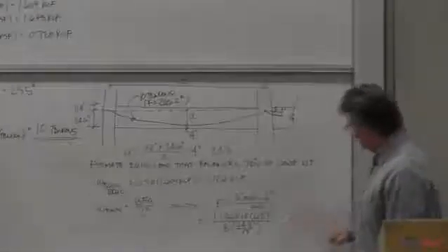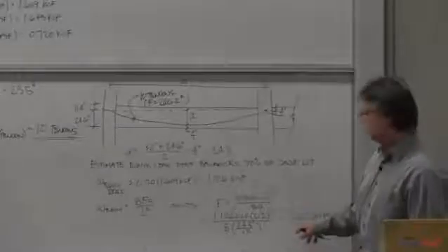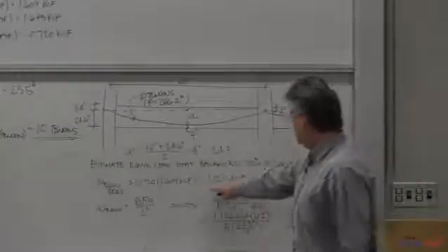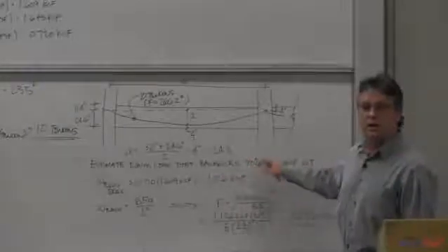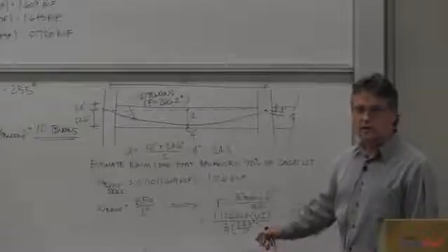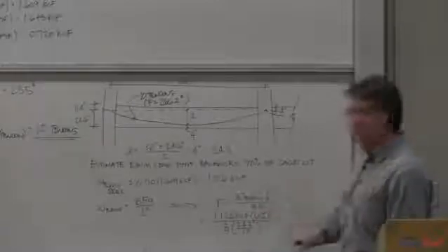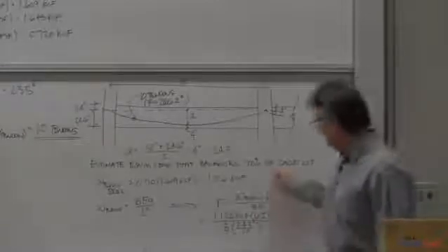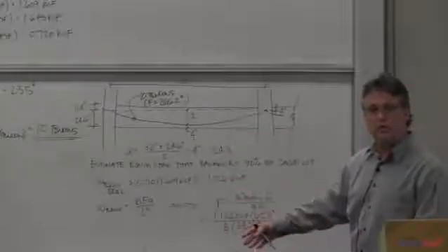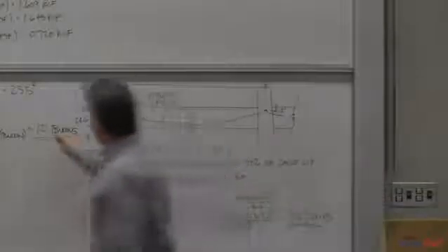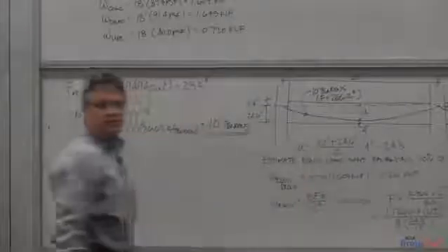Another thing that people do is then they'll tell me that this is the force. This was an estimated force. This was an estimated equivalent load. This was an estimated amount of concrete balance. None of these matter. None of these are numbers you're going to use in your calculations. These were numbers we were coming up with to go from a wild guess to a pretty darn good guess. And all we got out of that right now was 10 tendons. 10 tendons has a force of 266.2 kips, not 267.